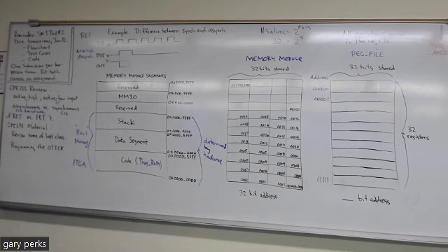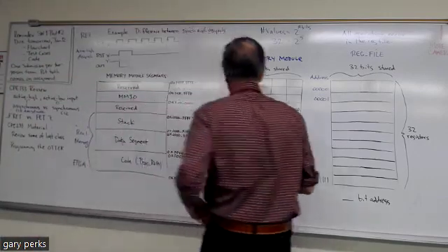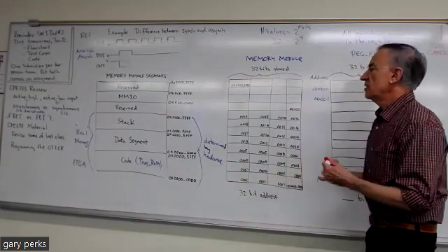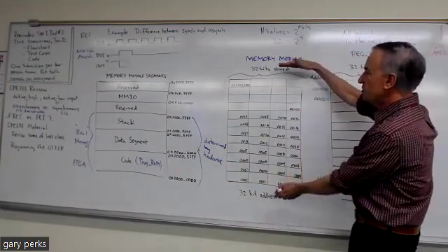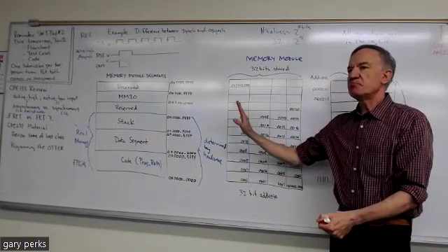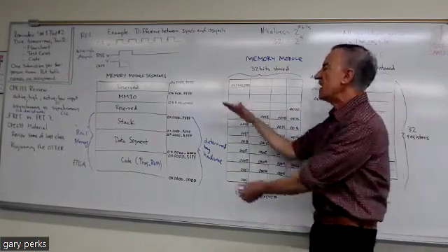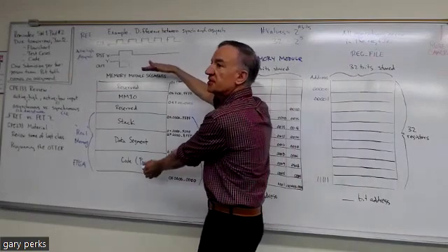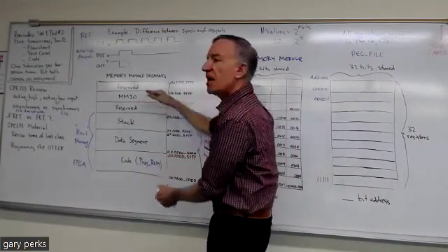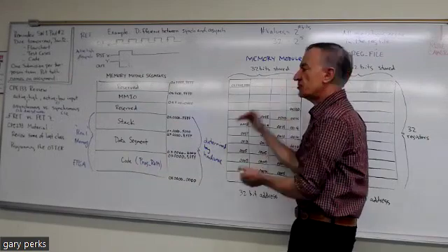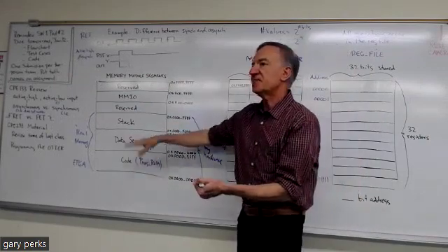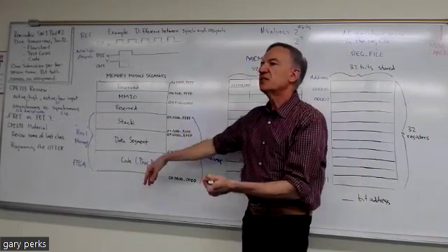What I'm showing here is the byte addressability of the memory module, and that applies to all of this. So the MMIO is also byte addressable, just like the stack is, just like the data segment is, just like the code is.